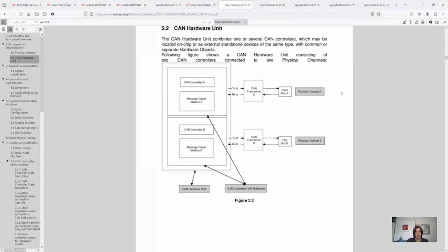And this usually is also a CAN connection, which then is only needed during the period of development and not in serious production. So you will have a CAN which you need during the development phase, which then is not needed anymore in the series project itself. But this you also have to consider. So you will have different CAN usually within your system.